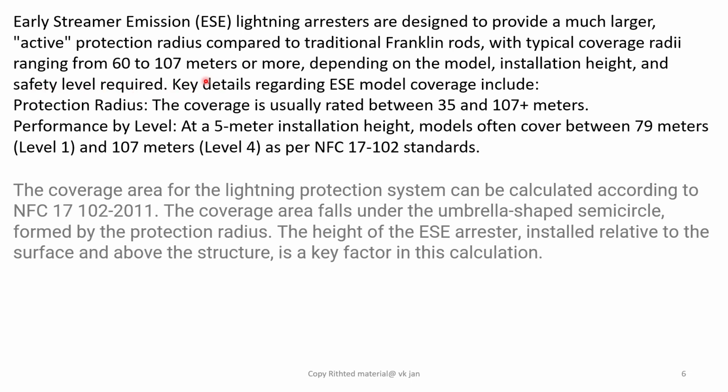Key details regarding ESE model coverage include protection radius. The coverage is usually rated between 35 and 107 plus meters. Performance by level: at a 5-meter installation height, a model often covers between 79 meters at level 1 and 107 meters up to level 4, as per NFC 17102 standards.